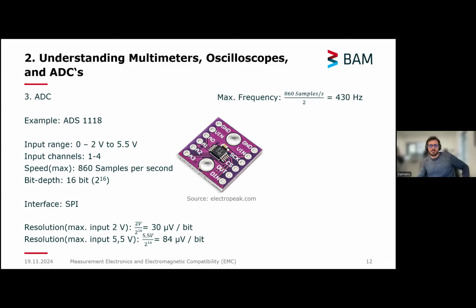Okay, thank you. And also it would be an embedded systems question. You have that analog digital converter and you have an interface. You have to connect to that chip and read it out via special drivers, being read out by a microcontroller, for example. So it's not a device you plug into your computer, but you still have to use a microcontroller to talk to this analog digital converter.